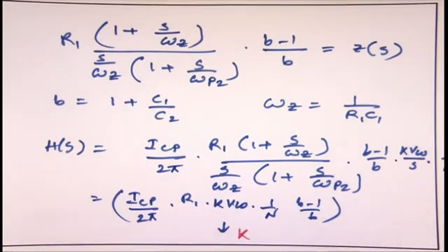What do you mean by instability in the PLL? PLL is not a linear system, correct? I already told you, but in terms of the phase, it is linear. So what do you mean by instability? Instability means in the phase domain. It is possible that if you don't design your filter properly with K VCO and all these things, you might get a phase instability, because the PLL is a phase domain linear transfer function.